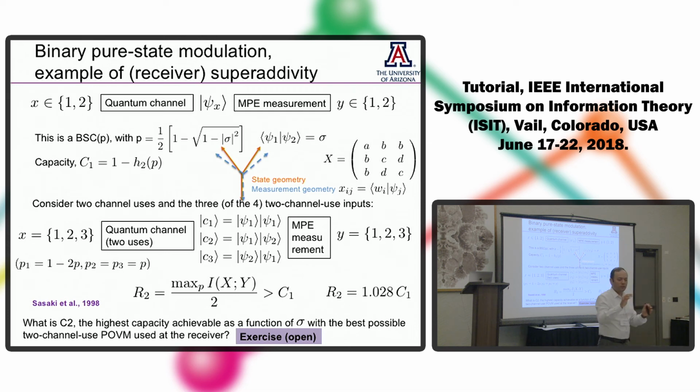Okay? And all of these standard receivers, be it optical communications, RF communications, all of them are C1 type measurements. The transduction part, the detection part acts on every channel symbol one at a time. Okay, you can do any amount of post-processing, soft information decoding, adaptive processing, any of that, but the moment you transduce, the moment you detect one channel symbol and convert it to the electrical domain, you are done. You cannot go beyond C1.